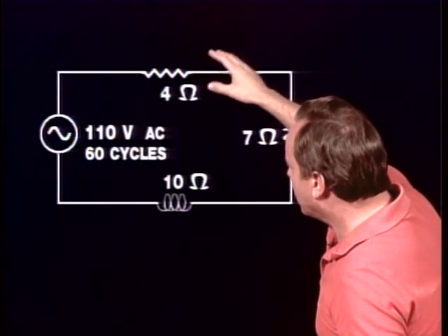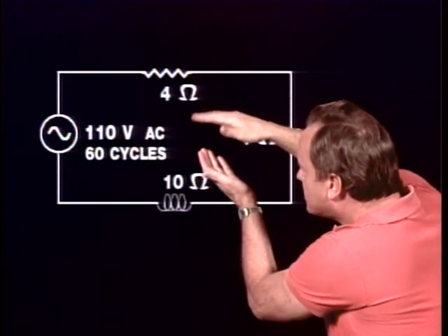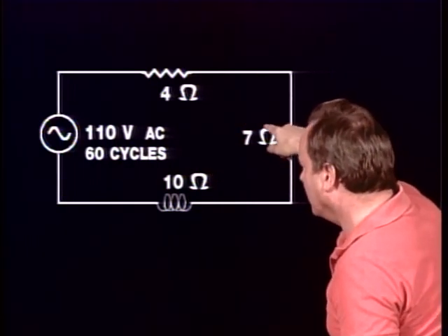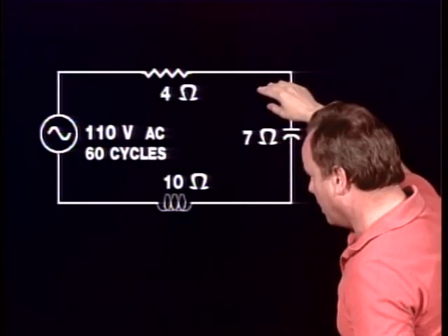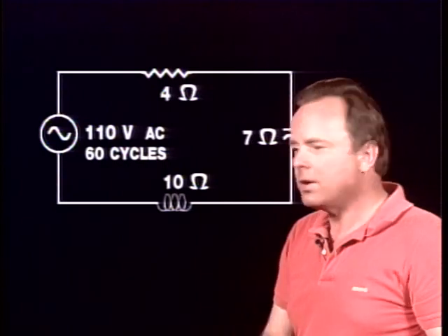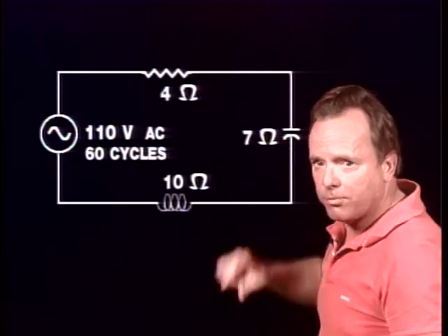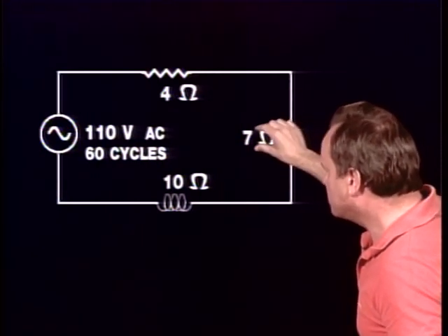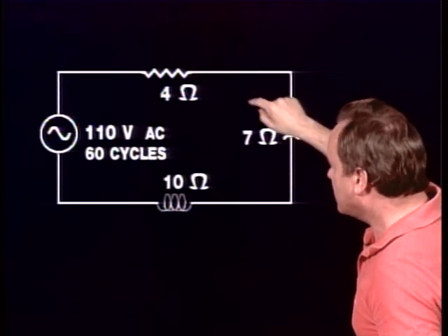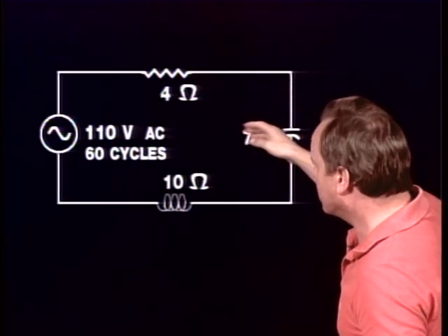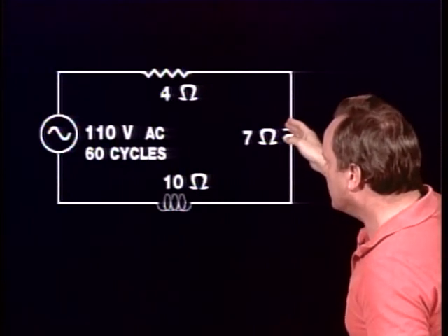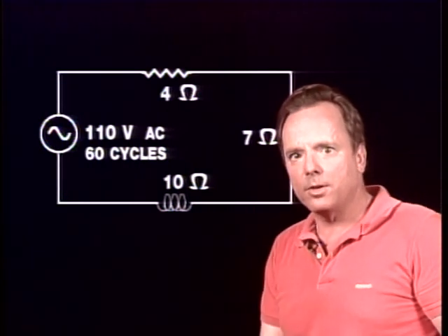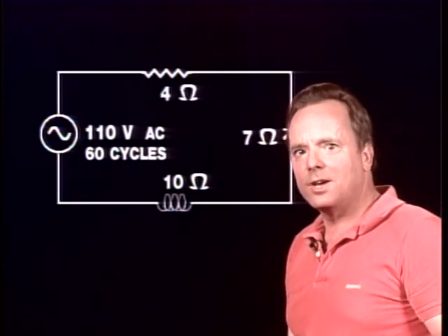But if the alternating current has a frequency to it, as the frequency increases, this capacitor tends to impede the current less and less because it charges the plate and it gives up its charge. Charges the plate, gives up the charge. And the faster the current changes in frequency and direction, in other words, the higher the frequency of the current, the less impedance is imposed by this capacitor here. And by the way, since the capacitor is almost like a short at first, it gives a place for the current to go, what happens is the current is about 90 degrees ahead of the voltage. Now with inductance, remember that the current's about 90 degrees behind the voltage, and this is going to become important.